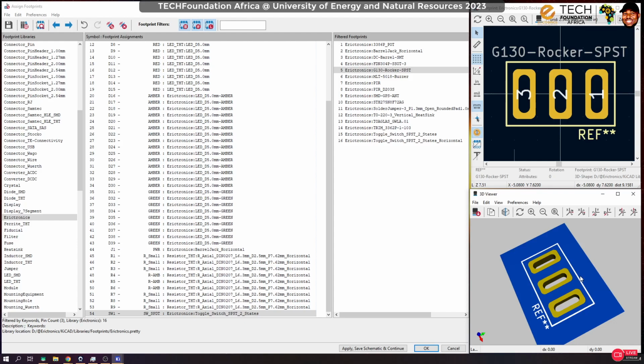Sure. Okay, so yes. Looking at this, let me see. Can I measure the diameter? The pitch from here to here. Okay, so there is a ruler here. From here to here is 4 mm, right? So I have to physically measure that and be sure. Actually, the one I have is not 4 mm. It's about 6.5 mm. So that is not what I'm looking for now.